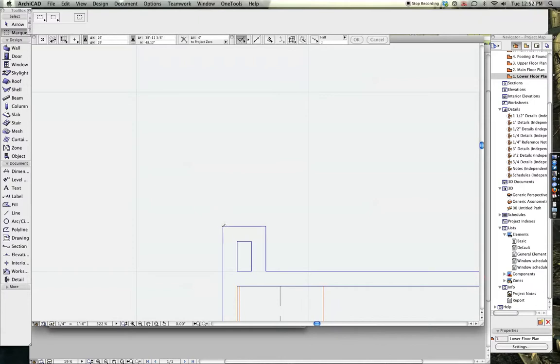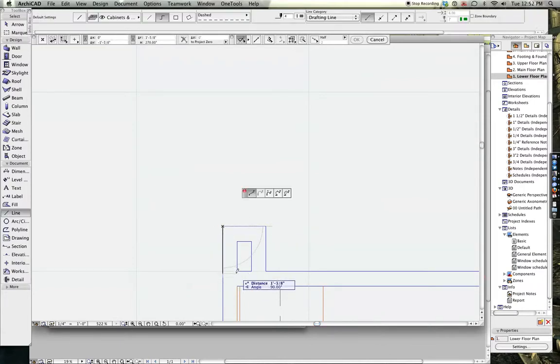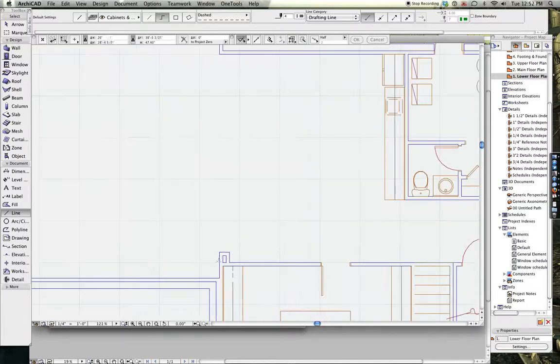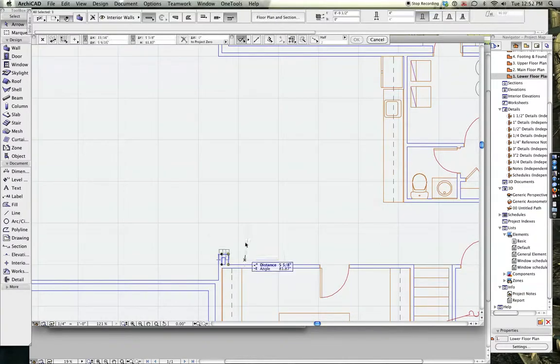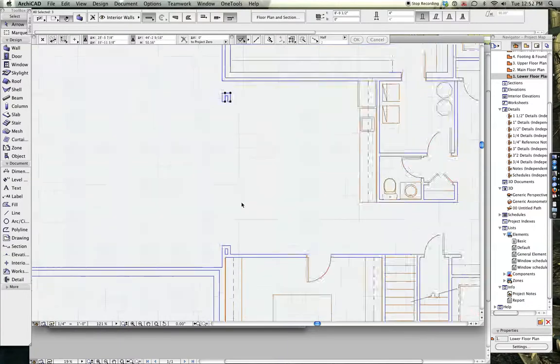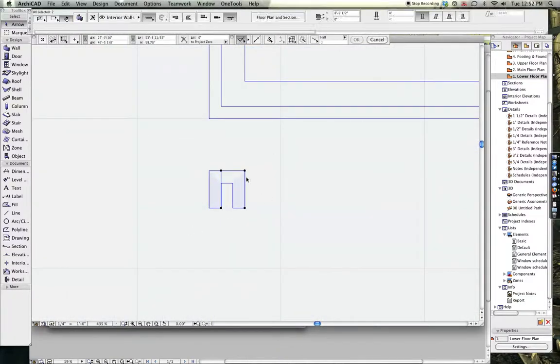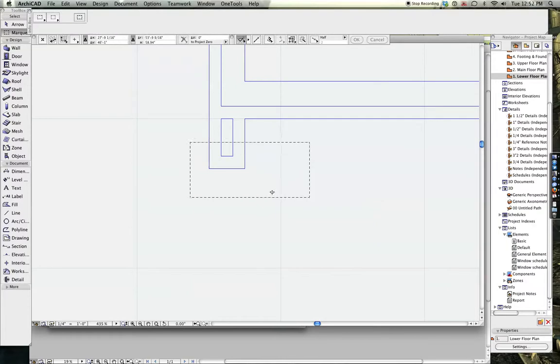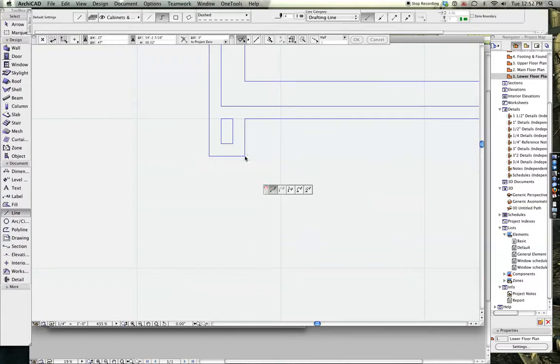Okay, that's a little bit messy, but we've got to fix it. So that's going to be 1 foot by 1 foot. Okay, same thing on the other side. We're going to drag it up, drag a copy, so Command D and then the Option key to drag a copy. Take these, we're going to project it, put them right there. Take this, put it right into place. Then this is going to be about 4 inches too big, so we'll just stretch that back using the H key. So number 2 invokes the marquee, and then the H key stretches, and then we just type 0-4, and that should be that right there. Okay, we'll keep going on a different recording.